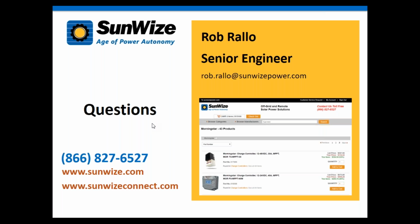Generally, you're going to find that a bypass diode is installed every 18 to 24 cells. And by the way, that is required by, I think it's UL. That is required by code. That's why they're in there. So it's required by the module manufacturers to have it in there because of that. Because without that, you get that shading, you can create that hotspot, and that can become a hazard.